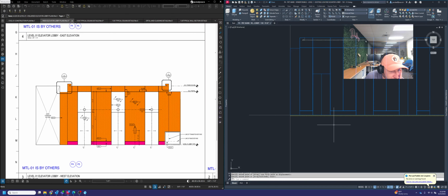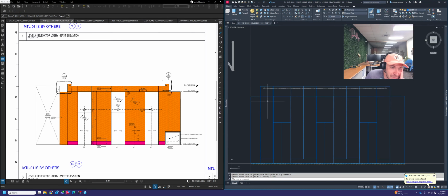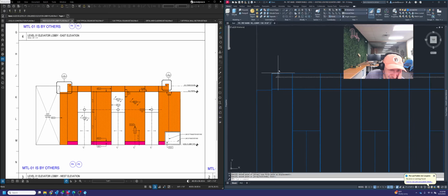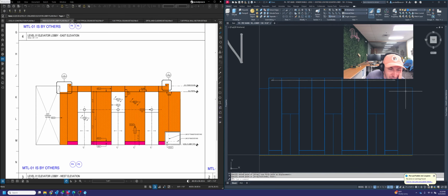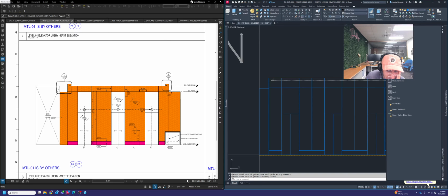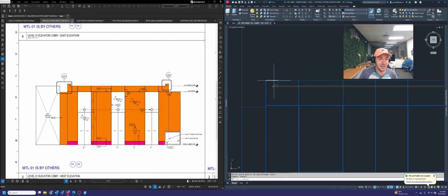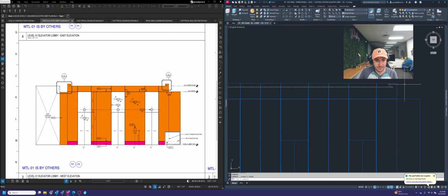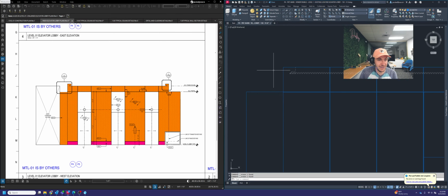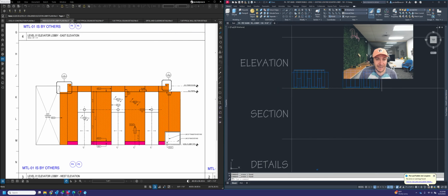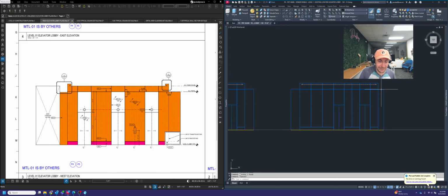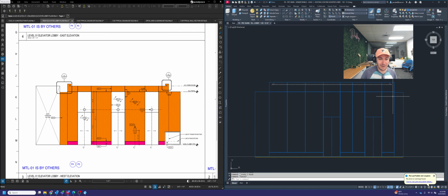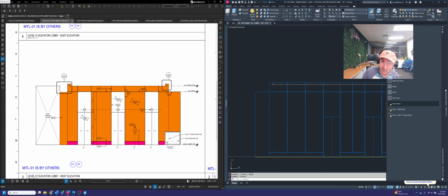Once I've done that, then what I want to do, because you can see I have this kind of complex shape that I need to hatch. So the hatch block for the wall, floor, and ceiling does an okay job of this, but not to what we need for this type of deal. So what I want to do for this thing is I'm going to actually trace out the ceiling with a polyline, and then I'm going to offset the polyline 2 inches out, then close the polyline and then hatch it with my tool palette hatch for walls, floors, and ceilings here.